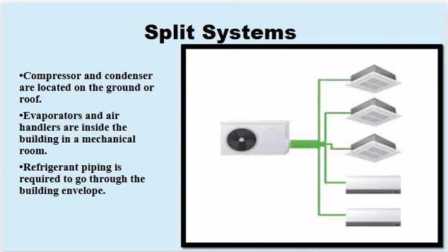Component division. This division allows for more efficient use of space, with the noisy and bulky compressor and condenser situated outside, leaving only the air handler and ductwork inside the building. Multiple indoor units. Split systems are versatile in that they can accommodate multiple indoor units connected to one outdoor unit. This allows for decentralized temperature control, giving flexibility in large multi-zone buildings.